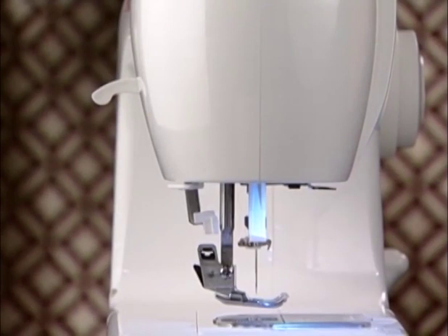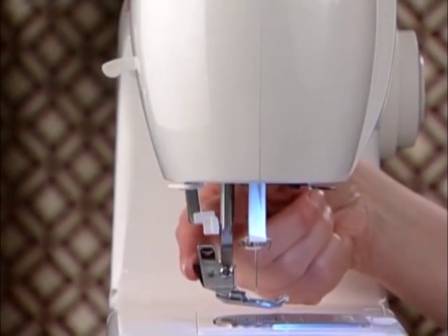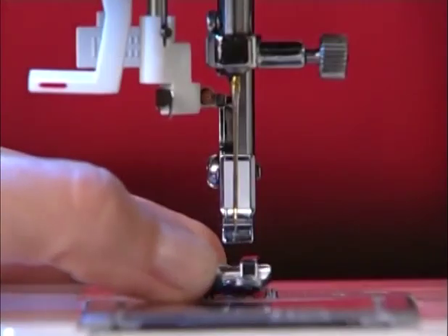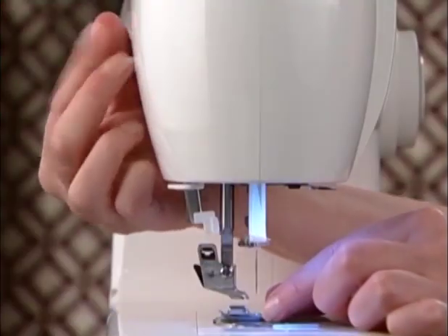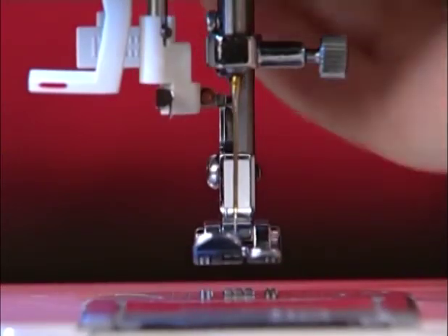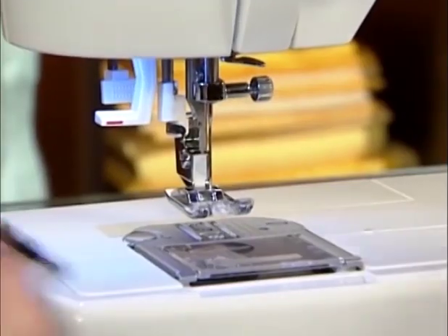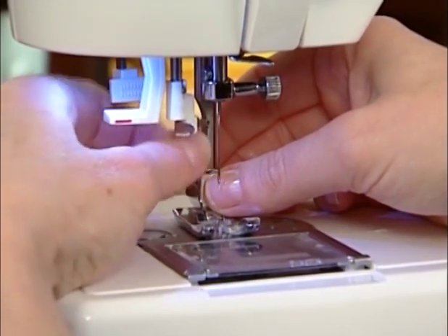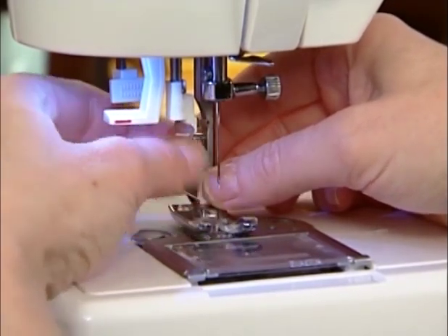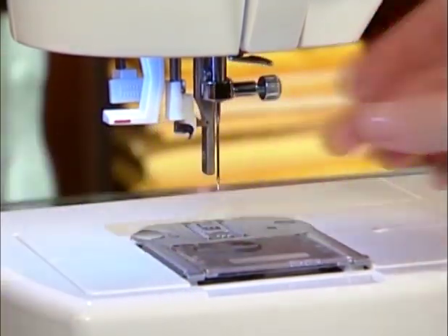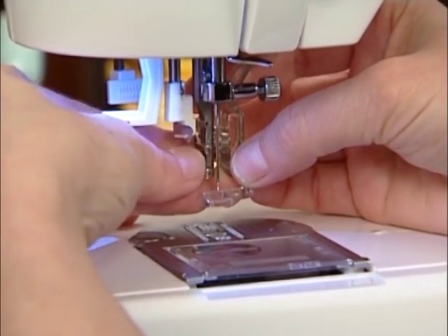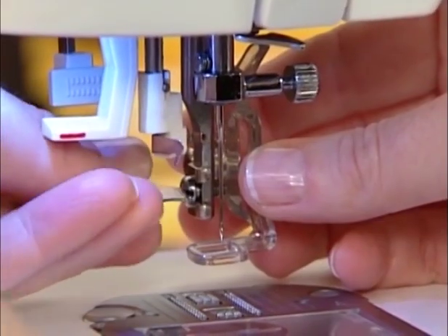Some machines have a shank with a release button or lever. This is pressed so that the foot releases. Place the desired foot on the needle plate, aligning the foot holder with the presser foot pin. Lower the presser foot lifter so that the foot holder snaps onto the foot. Some feet already have the shank attached, so it will be necessary to remove the shank currently on the machine in order to put the new foot on. Use a small screwdriver to loosen the shank on the machine and completely remove the screw. Set the new foot and shank in place, then replace the screw and tighten it securely.